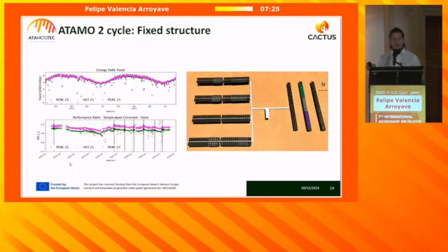So in this sense, we saw that effectively something that we were realizing is that technologies with high bifacialities are very sensitive, at least in fixed structures, to the soiling and to the cleaning.